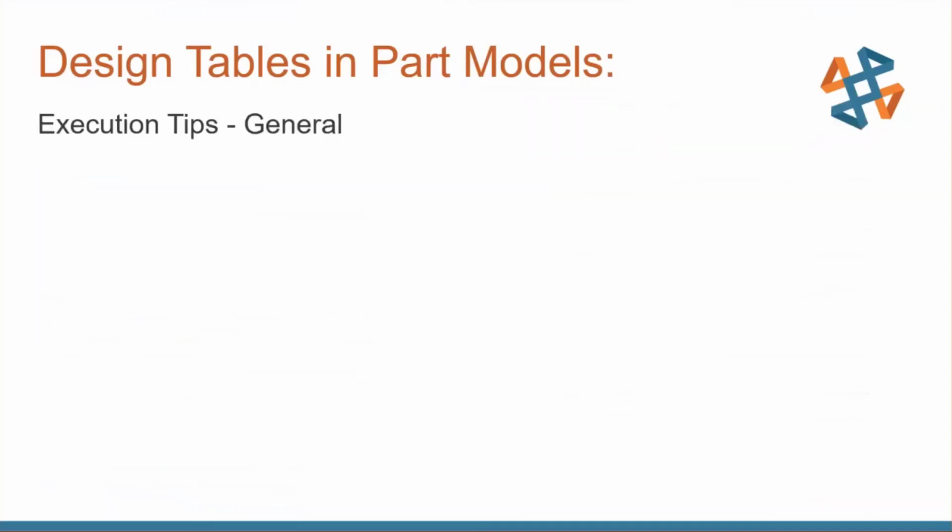So a few general tips. This is just really basic here, but start simple. It may seem like a no-brainer, but I can't tell you how many times I've worked with customers that have gone so far into a design table that nobody else can edit the table, nobody can work with it, you can't share the data with anybody. So just start simple, make sure everything works, and then expand from there.